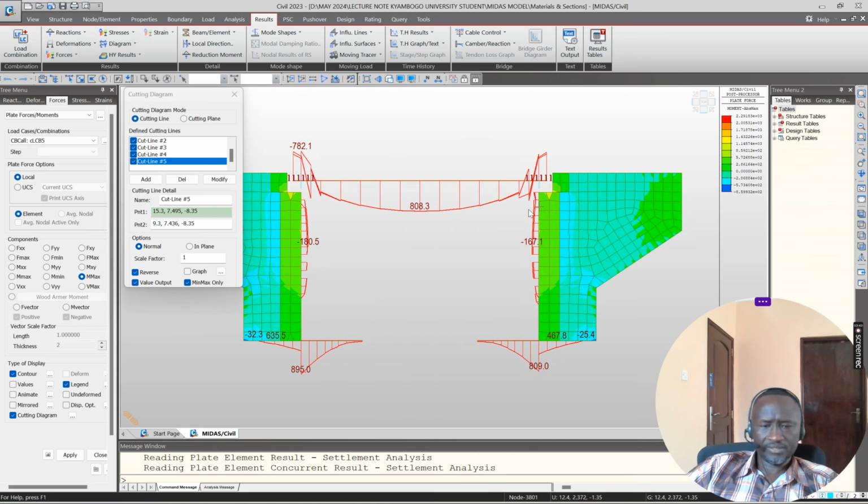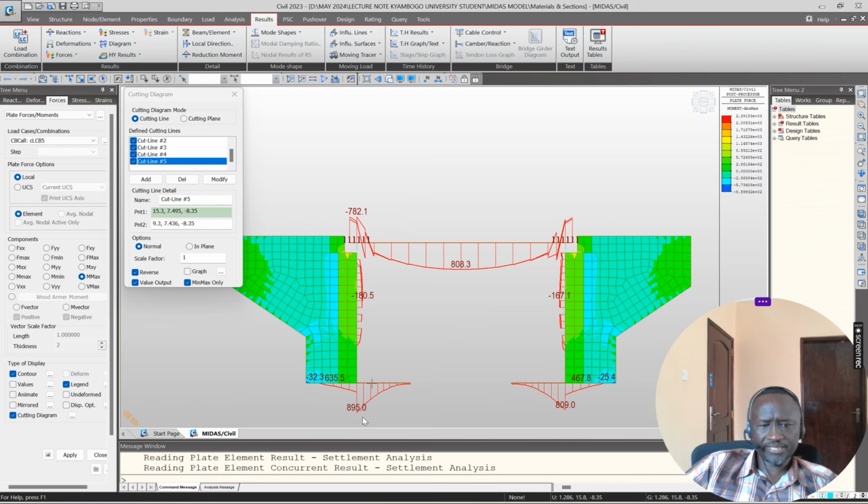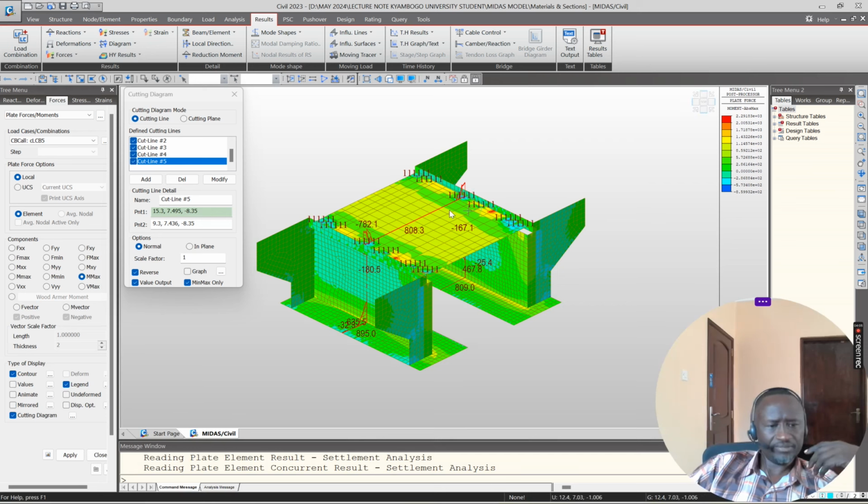It is simply supported, but because the bearing is slightly in, you have a hogging effect. It is simulated as a bit of a cantilever because the bearing is 0.44 meters off the end of the girder. So you can look at this behavior, look at the abutment, look at the foundation. This is exactly what you will be looking at when you are doing your work.